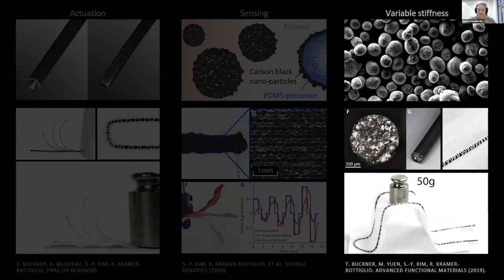Okay, and for the final functional fiber, for the purpose of variable stiffness, we developed this particulate composite made from low melting alloy particles in a thermoset epoxy, which displays a nearly 3 orders of magnitude change in modulus in response to thermal stimulus. So the Fields metal epoxy composite can be manufactured in fiber form and integrated into the fabric by couching, which is how we also integrate the SMA ribbons. By actively softening and stiffening the variable stiffness fibers, we can regulate the degree and direction of fabric actuation with higher repeatability and fewer total actuators. And an on-demand support structure allows the robotic fabric to perform move and hold operation or hold loads, which would otherwise collapse a typical fabric.